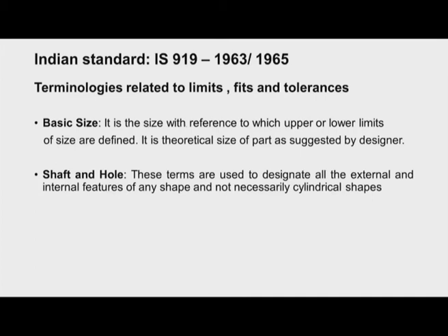Now, we should understand what is the meaning of basic size. It is the size with reference to which upper and lower limits of the size are defined. It is the theoretical size of the part as suggested by the designer. So, the design engineer will make some calculations, and finally he will arrive at some size for the shaft, say 25 millimeter.